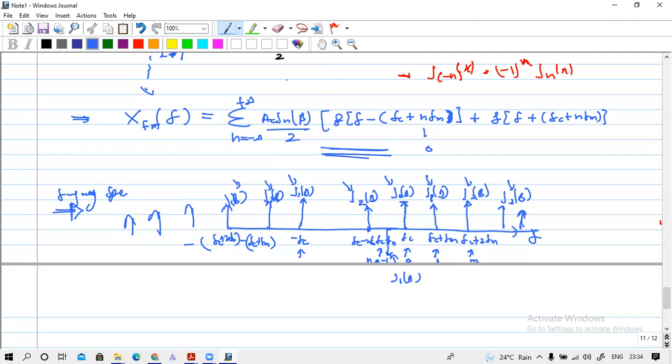So you can see that this is for a sinusoidal signal. So if you want to find the power spectrum, you can simply take this value squared. So you have J2 beta squared, J1 beta squared, and also Ac by 2 is also there.